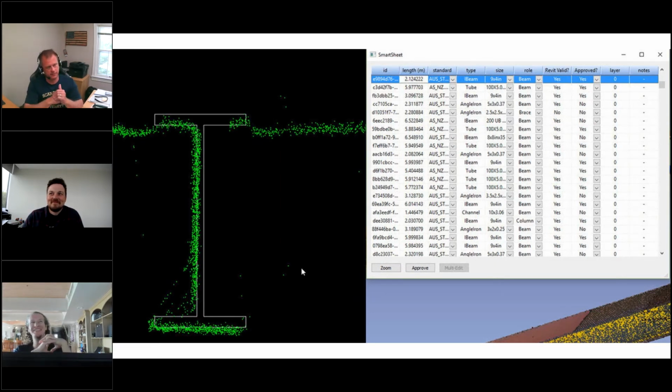But when you use an automated extraction tool and you have 800 beams or 800 pipes, you need to QA them to make sure the algorithm did a good job, and to get rid of the bogus stuff, like ends of concrete bags or handrails. The fastest, easiest way to do that is using a spreadsheet, sorting by different parameters and metrics that we teach our customers how to use, and quickly dumping out pipes that don't meet certain criteria.